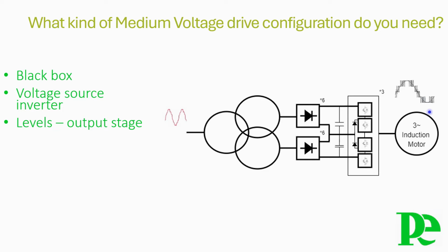Some manufacturers also offer a 5-level inverter, but it must be noted that if the 3 or 5-level inverters are to drive a standard motor that is not inverter duty, these inverters will require a sine wave output filter in order to reduce the common mode voltage and the voltage stress on the motor. These supplemental output filters can be of a significant cost and might also introduce performance restrictions on the power drive system.